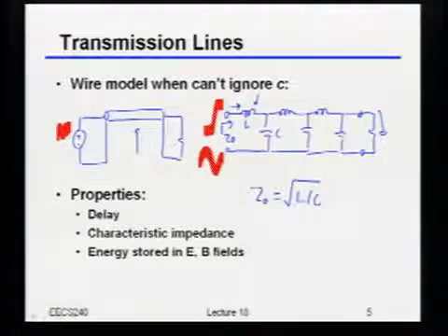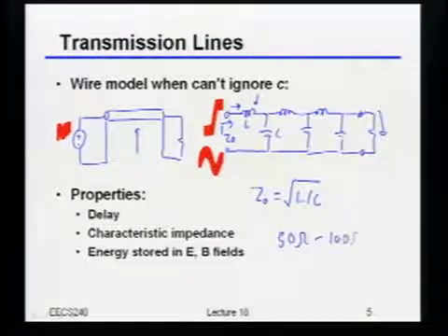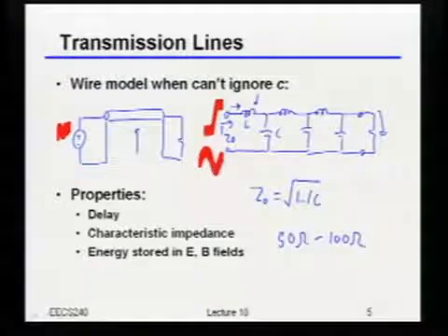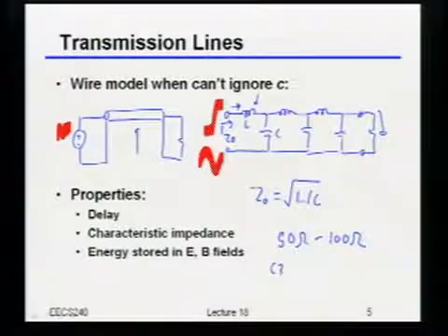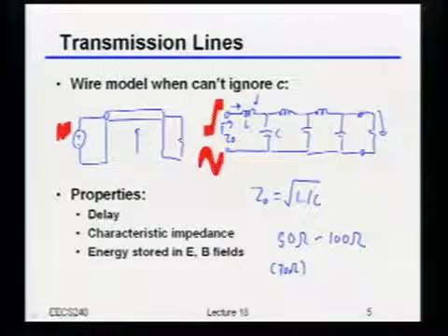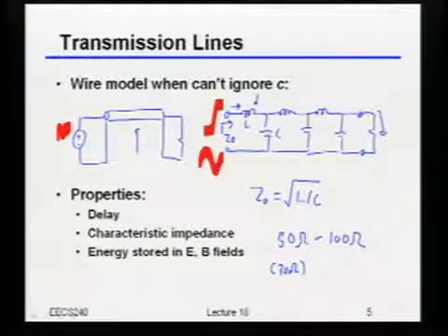Again, it's one of those classic EE240 problems where they give you an infinitely long network of repeated things and ask you what the impedance is. Same exact thing, so that impedance is going to be square root of L over C. If you look at typical transmission lines, even on our PCBs, that Z0 is typically somewhere between 50 to 100 ohms, maybe even a little lower, like 30-ish ohms on the low end. But not too huge of a range, and actually a fairly low impedance.